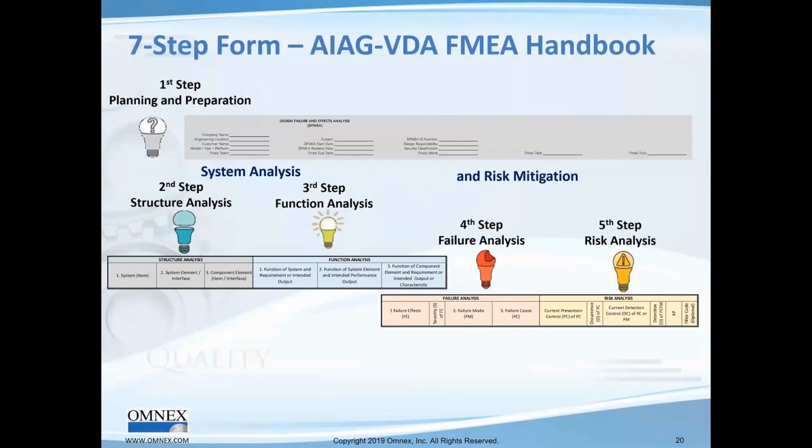You can start maybe at the focus level. That's what's numbered here as 2. Do you see that? All right. And then to the left-hand side of it is the effect of that failure. And now, because you have come up with function analysis and you have functions and requirements, this failure of this requirement causes this failure in this higher level requirement and is caused by this lower level requirement. So that's the fundamental way the AIAG VDA FMEA works.